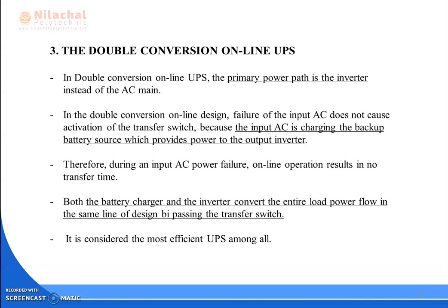Therefore, during input AC power failure, online operation results in no transfer time. Since there is no transfer switch concept, the time taken to transfer the load when the current is not present takes a very minimum amount of time.